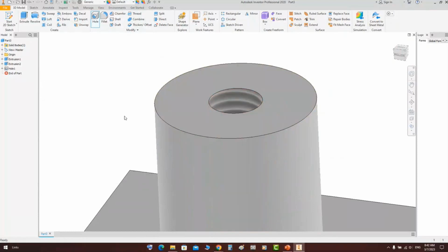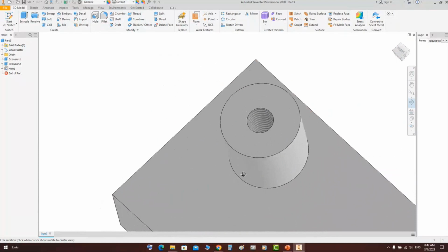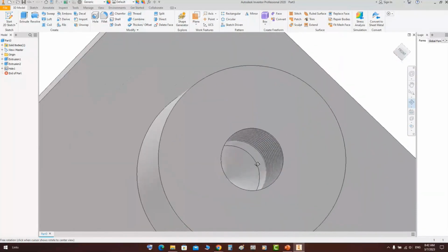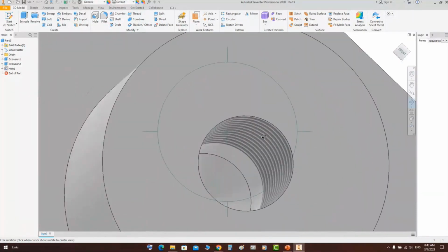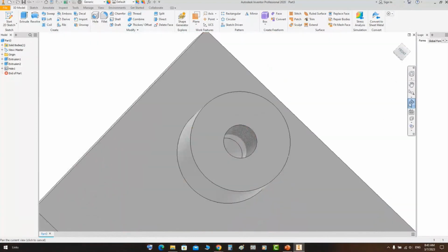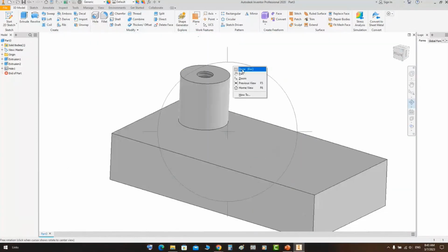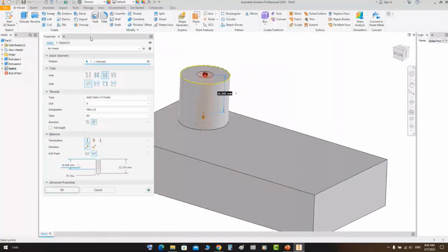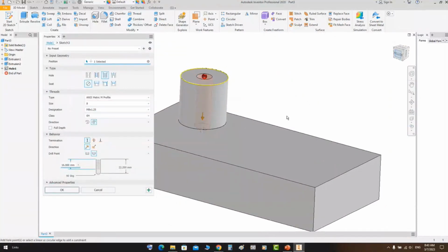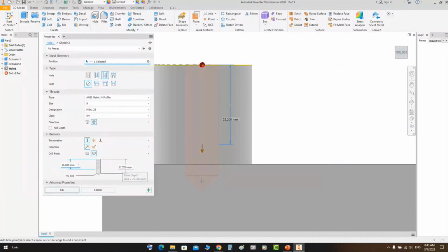on this sketch. Now, let's click on OK, and you can figure that you have a thread on this hole, not to the end, it's with 16 millimeters. Anytime you would like to make a modification on this one, just double click on the hole and you will get this form again, and you can make the modification like changing the depth, changing the angle, the thread length, or the hole designation and hole thread information. Okay, so that's the first option to define the hole.